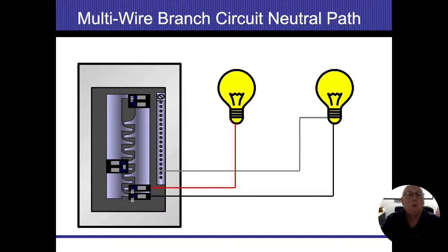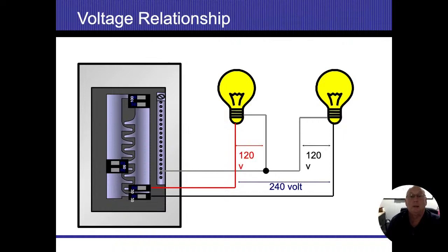So when I have these two breakers right next to each other, even though they're both on the right side, just because of this staggered bus bar, the bottom breaker is taking its electricity off the left side. The second from the bottom breaker, or the one where the red line goes to it, is taking its power off the right side. So they're both opposite phases. One's getting when it's positive, the other one's negative. So now we energize that on the opposite phase. We bring our neutrals back in here and everything back. Both light bulbs are going to work, and we made our connection.